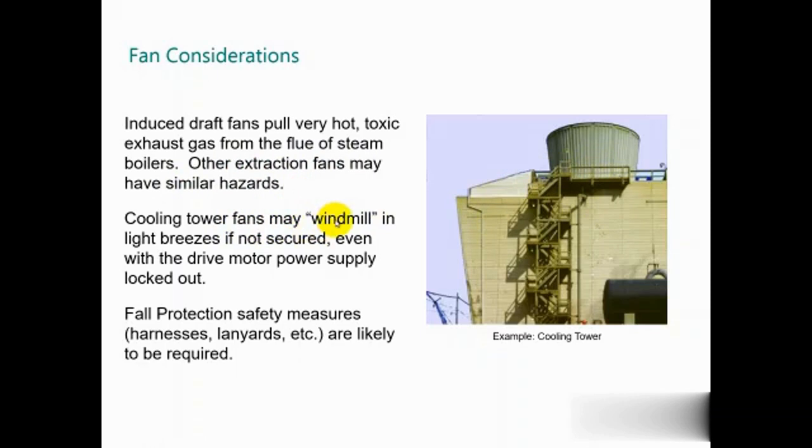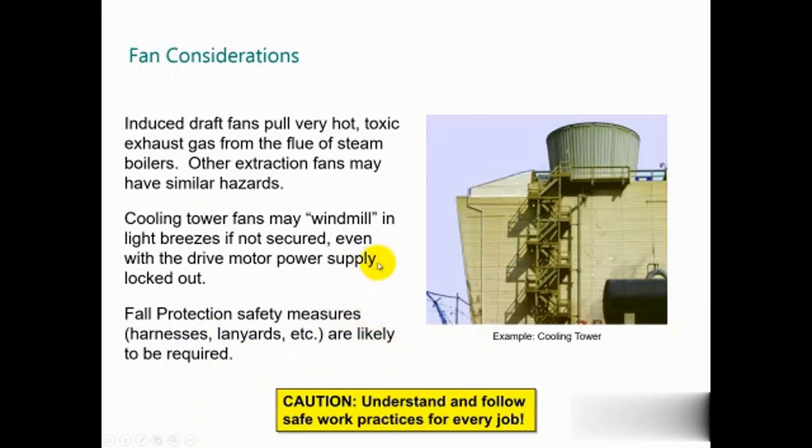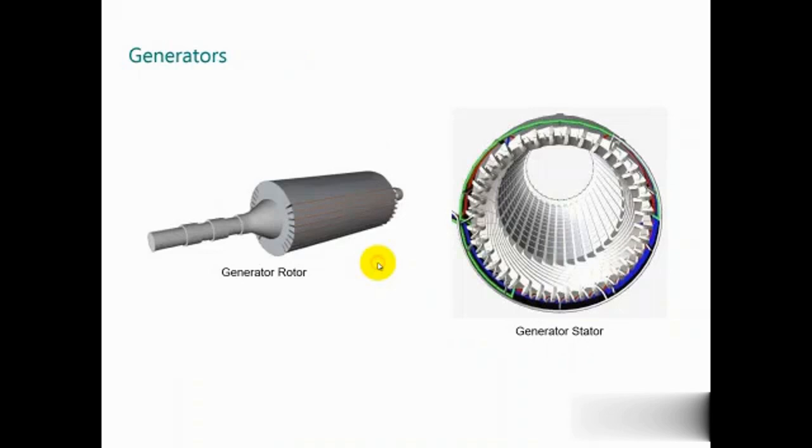That means any very soft blow can start to move the blades. You need to ensure that the blades are locked, and you need special devices because you are working at height: harnesses, lanyards, etc. Remember, understand and follow safe work practice for every job.